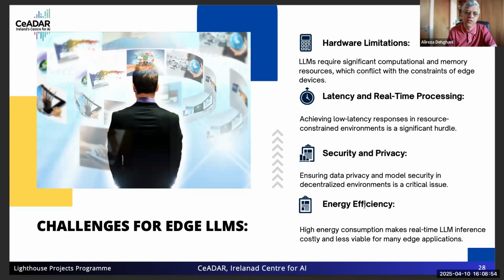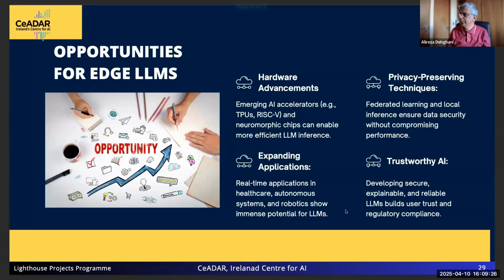Because power consumption was very important for us, I remember at that time we used to benchmark it on different hardware, and the Movidius platform was always on top in terms of power consumption. So it was like, okay, with the Movidius platform, you can drive your drone for 10 hours. With another platform, it is possible to do that for only 6 hours, which was a very important and crazy aspect to consider. So energy efficiency is again important, as I said.